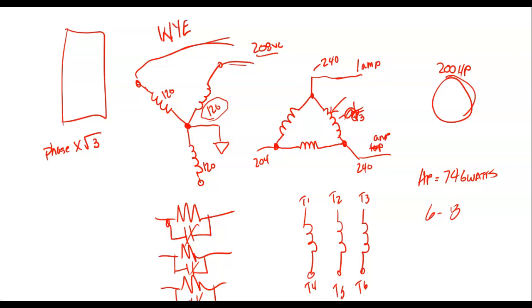So at US Steel, we had these, and they would automatically switch it. It'd have a timer on there. We'd start the motor. It would make it go through the resistors. After 15 seconds, it would drop out, and then it would come up here, and the motor wouldn't tear everything up. So that'd be like you getting in your car. You've got a 500 horsepower car. You get in your car and slam the gas all the way down. What's going to happen?